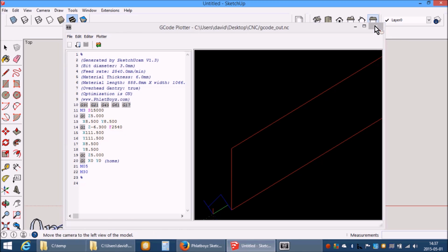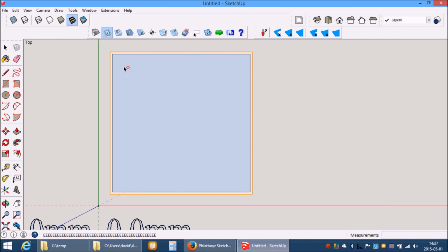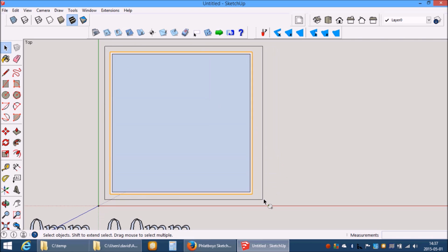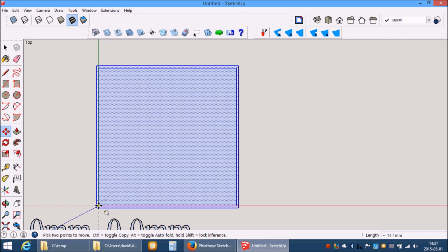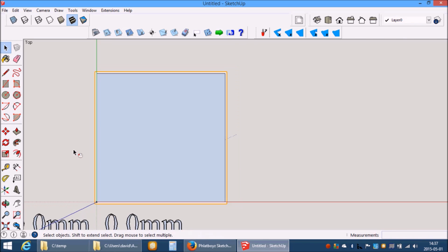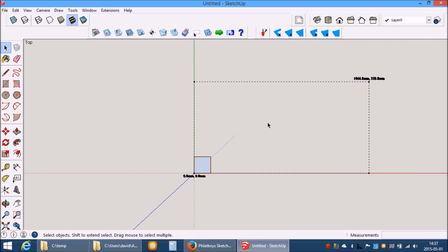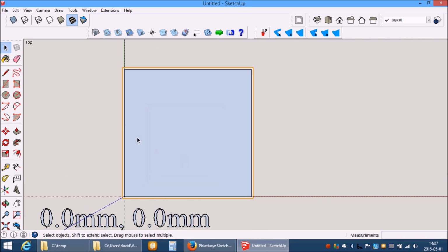Also, one must be careful not to have the cut lines exceeding the boundary of the safe area. As you can see there, this left hand side and bottom are now outside of the safe area, and Gcode will not be correctly generated for those lines. In fact, some very odd things may well happen. Do not let your cut lines overlap the safe area lines.